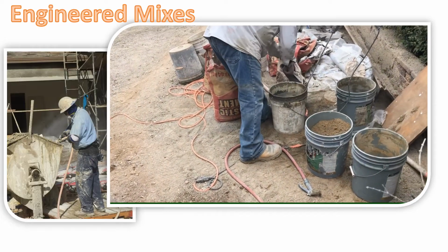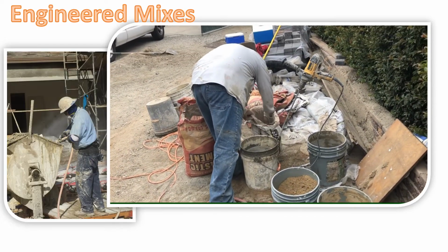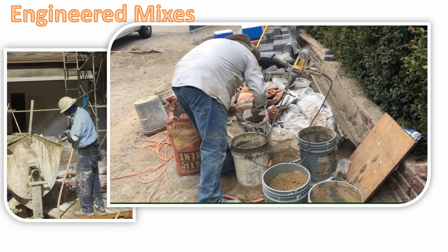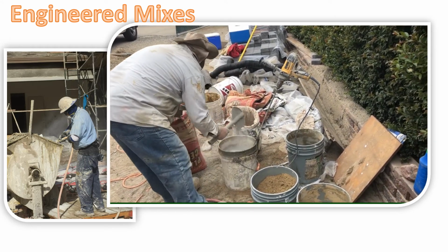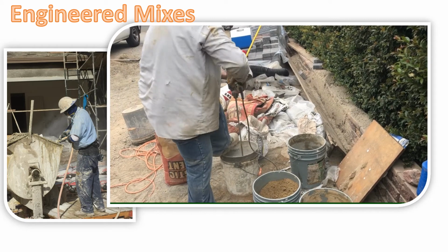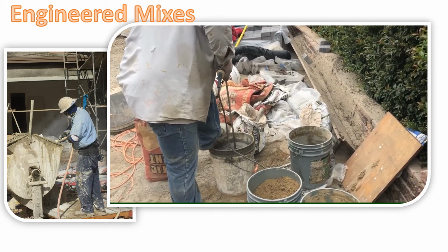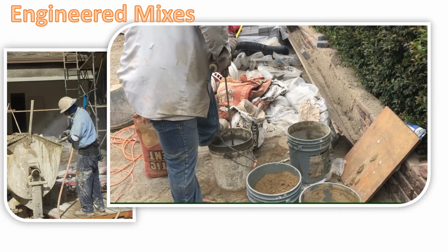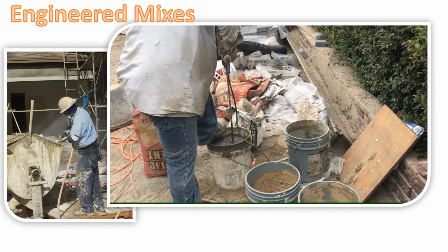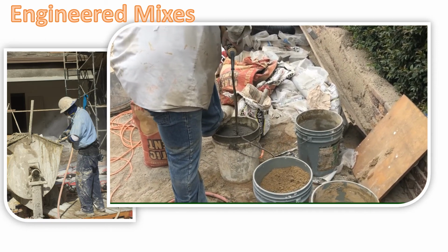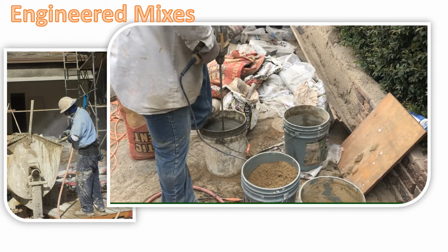Generic mixing of plaster is risky, and why the SMA urges the use of what we call engineered mixes. These are mixes blended at the factory to meet and comply with code requirements. While they may add a slight cost to the stucco project, they tend to be less risky and ultimately of better value in the long run.